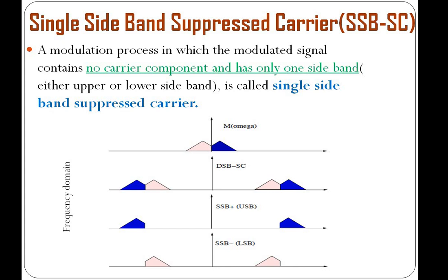That is more than enough for your modulation. Whatever the bandwidth your message signal has, that much bandwidth is enough for our sideband. If you are using two sidebands, we require twice that of your message signal. Why should we unnecessarily waste the bandwidth, right? Whatever the message signal you have, that message signal's equal bandwidth is taken by one of the sidebands.